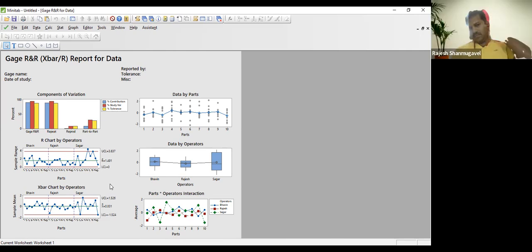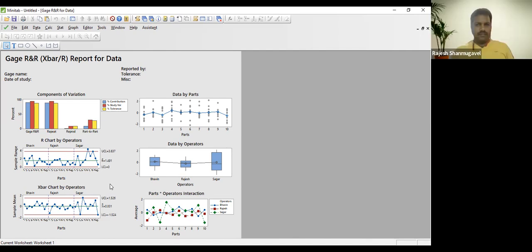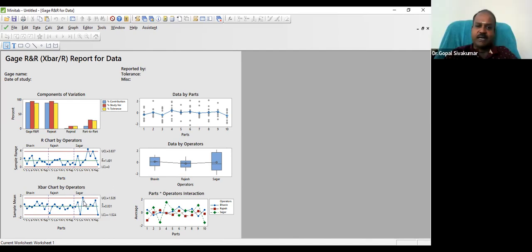If I have selected 50% good and 50% bad, but I see my measurement system is struggling to differentiate between good and bad, even considering bad parts as under control. The bad parts mean your process is producing bad parts, still your measurement system is not throwing them outside the control limit.